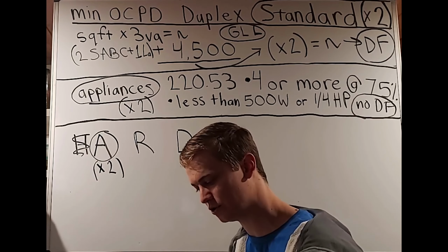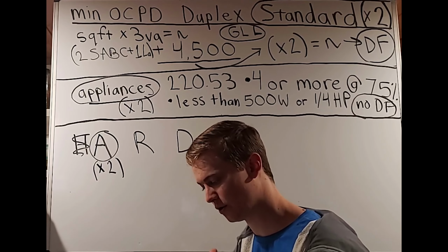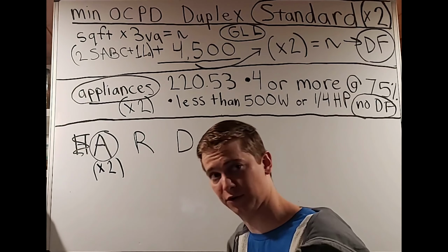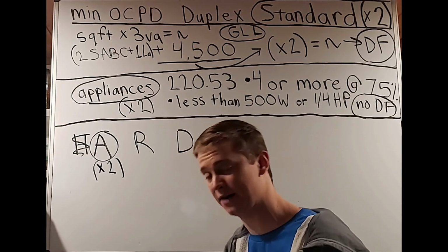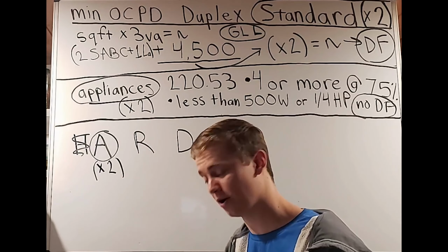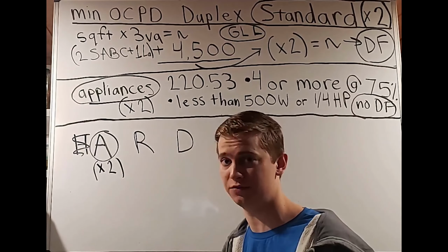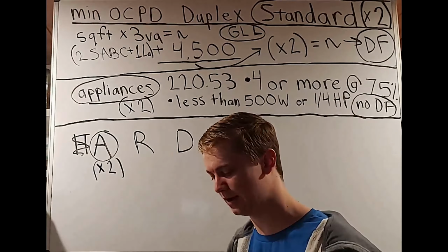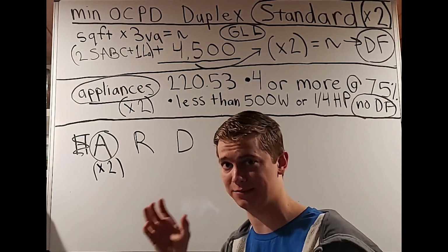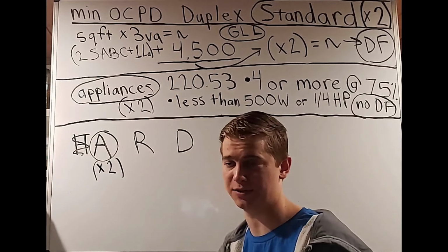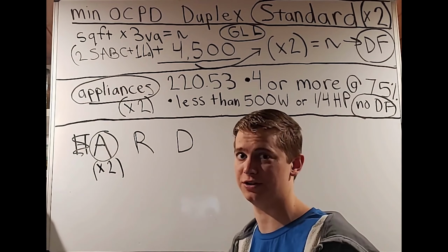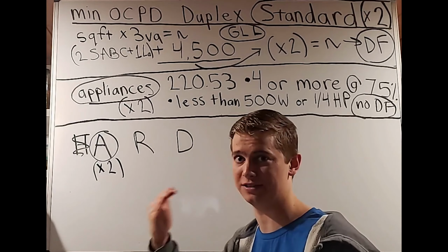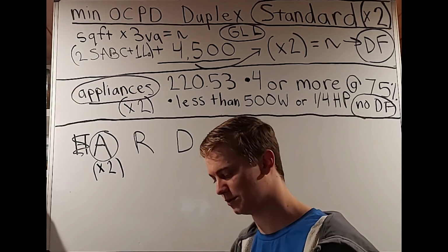We're going to then get into our ranges, which we do have demand factors. We're going to look at table 220.55 and we're going to use that table accordingly. Of course, you find out the kilowatt rating of your appliance and then how many of those appliances that you have with the same kilowatt rating. If they are rated differently, then they're going to be individual ratings. So of course you're only using the number of appliances section when you have multiple appliances that have the same exact rating. Again, like most stuff that I'm going to explain in this video, my residential load calculation video number 1 really goes in depth explaining all this stuff, and there's actually separate examples of the ranges to where you'll see how to use this table.